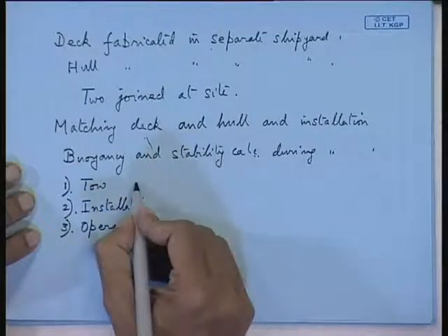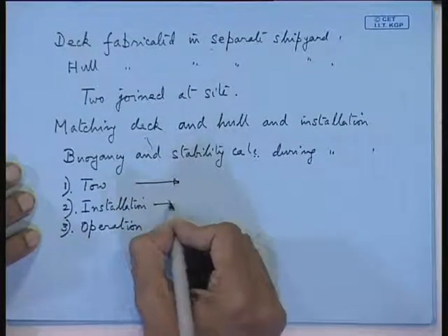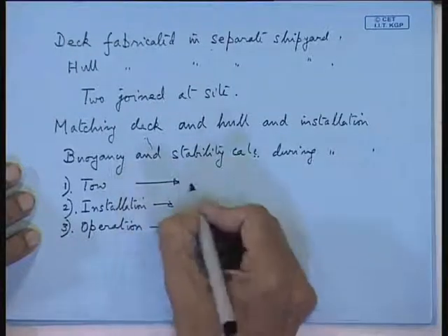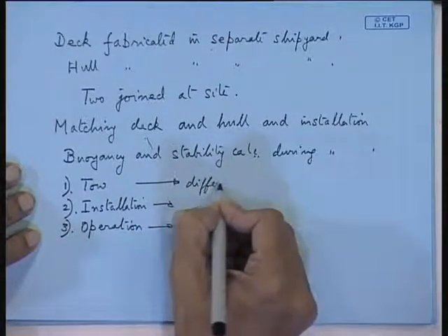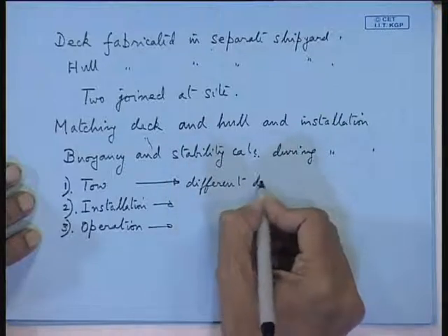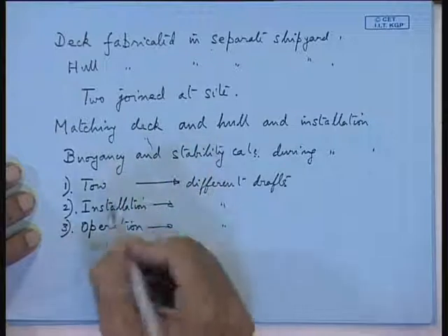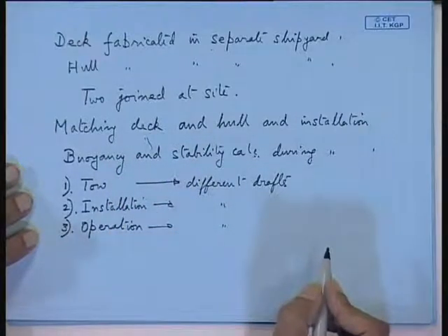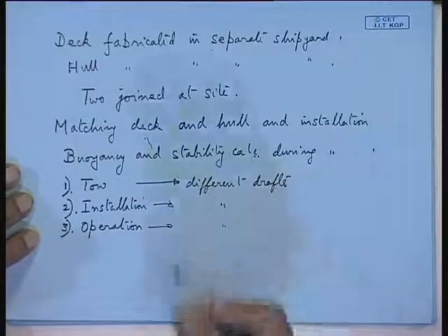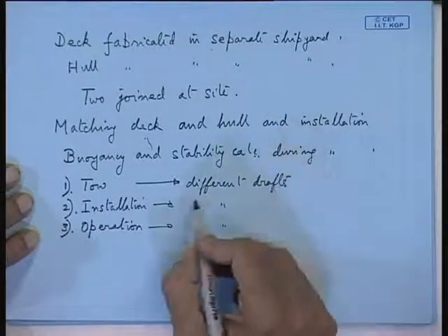So, these are actually different drafts. Now, you have to calculate these drafts during tow, installation and the operating mode when it is drilling or recovering oil. So, drafts are different.